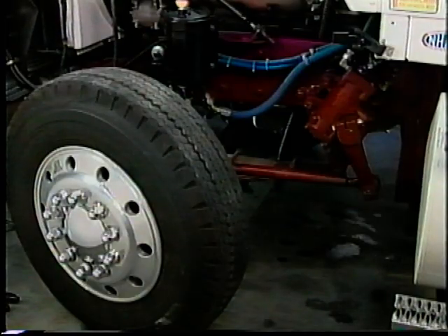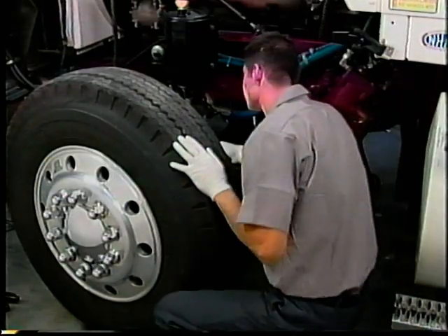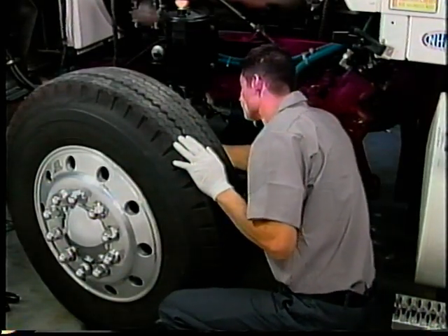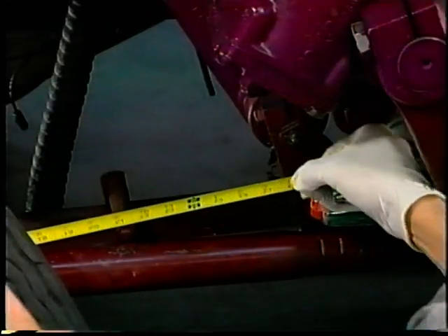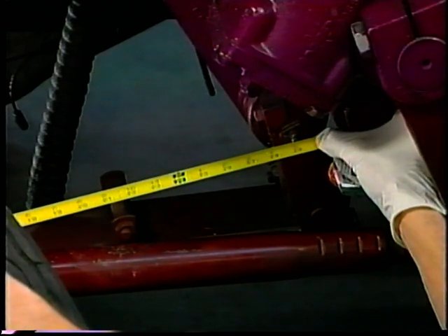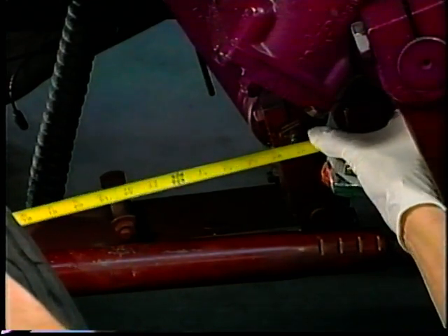Many truck front suspensions are solid I-beam axles sprung on multi-leaf springs. The axle is connected to the steering knuckle by kingpins. Problems with bent or twisted I-beams may not be visible to the eye. Measuring front wheel setback will give you an accurate indication of how true the I-beam is.